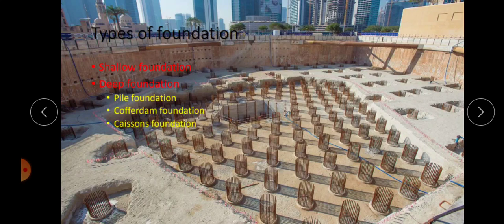So up to this we have discussed the different types of shallow foundation, design of shallow foundation, etc. So now onwards we can discuss deep foundation. Deep foundations are used when our surface soil is unsuitable for shallow foundation, that is, the hard stratum is very deep. In that case, the depth of foundation will be very high compared to the width. That type of foundation is deep foundation.